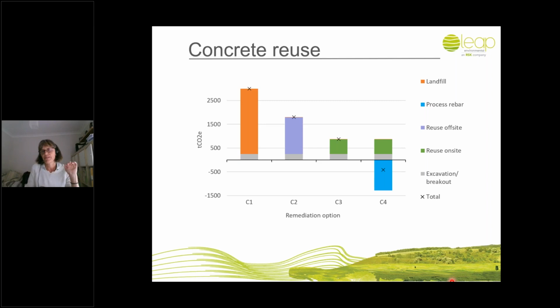I have to be slightly skeptical about this, and I'm slightly worried. I put this graph up and I'm always a bit worried that I'm greenwashing what we're doing. It's a bit too good to be true. I also know that the carbon factors you get for some things, like the carbon factor for glass, for example, differ. There's a carbon factor if you reprocess lovely glass that's all the same kind. And then there's the carbon factor for reprocessing stuff perhaps that we might have got out of the landfill. That glass can't be reused to make bottles. It's going to be reused for aggregate. So you have to make sure you've got the right carbon factor.